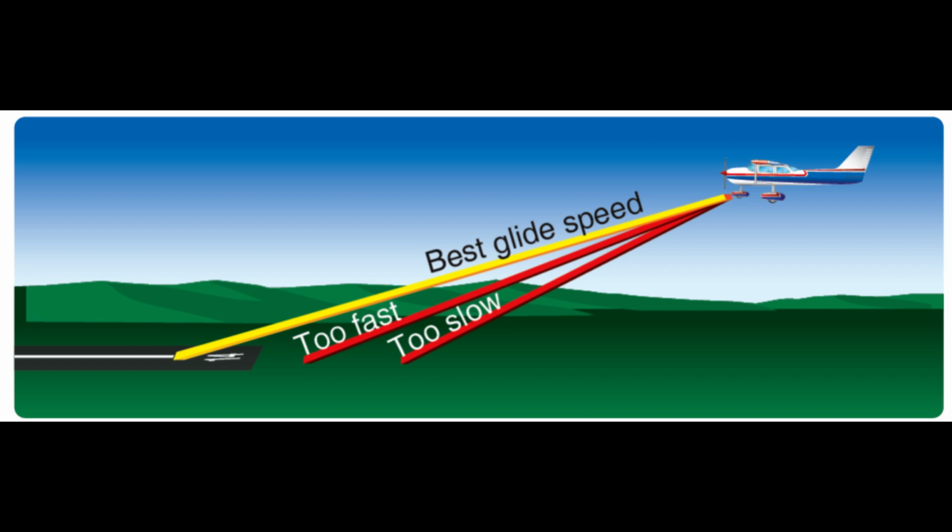2. During a power-off landing approach, the pilot depresses the rudder pedal with excessive pressure that leads to increased lift on the outside wing, banking the airplane in the direction of the rudder deflection. The pilot may improperly apply the opposite aileron to prevent the bank from increasing while applying elevator back pressure. If allowed to progress, this situation may result in a fully developed cross-control condition. A stall in this situation almost certainly results in a rapid and unrecoverable spin.